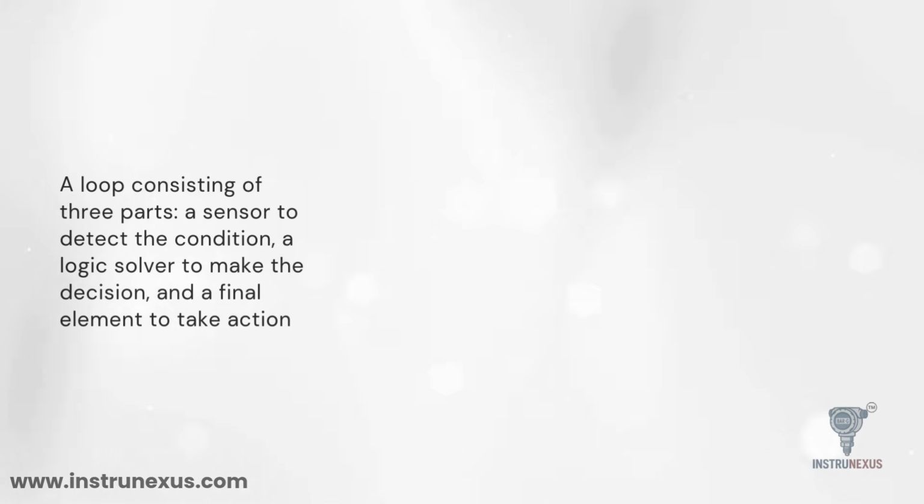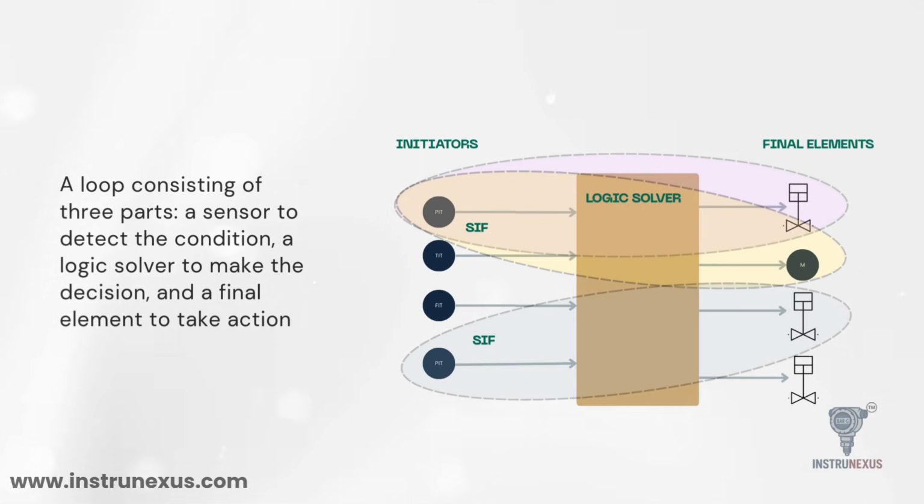It is crucial to understand that a SIF is designed to address a specific risk. It operates in a loop consisting of 3 parts: a sensor to detect the condition, a logic solver to make the decision, and a final element to take action.